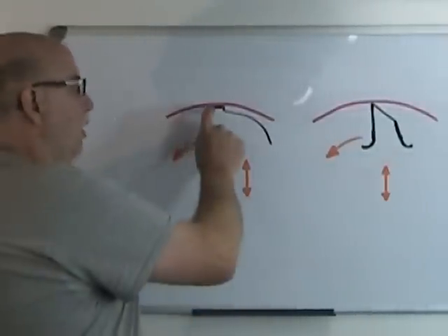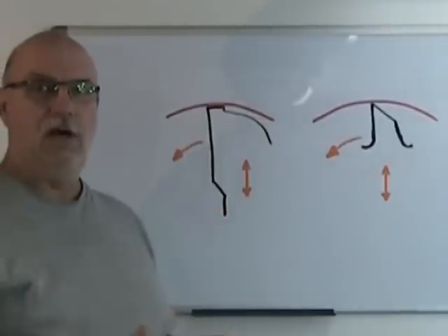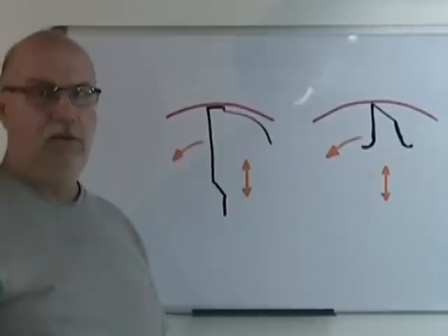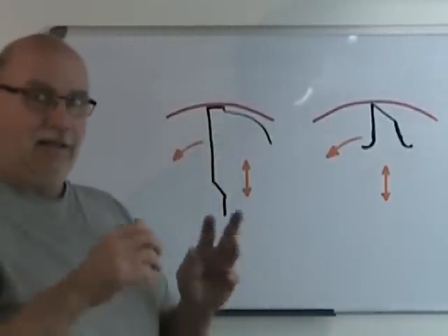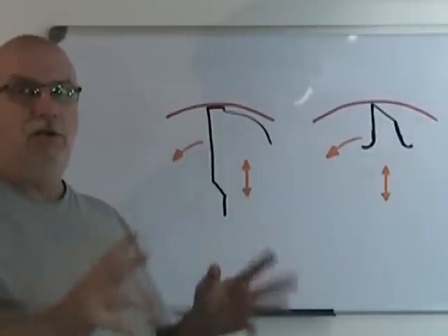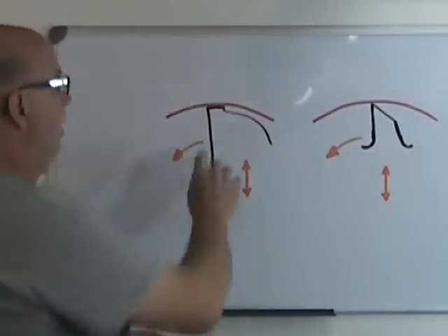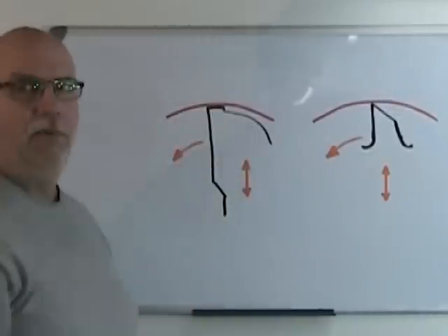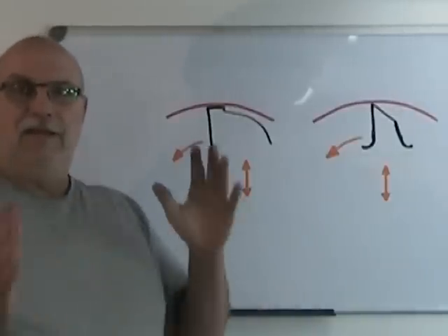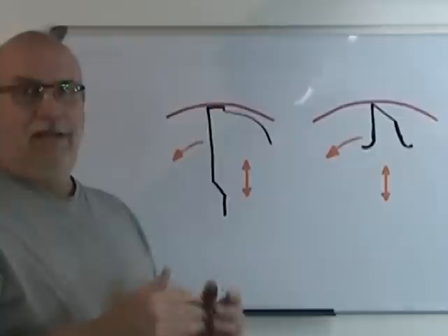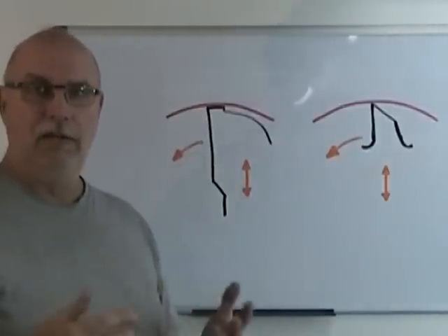Now, if these were cutting edges, the minute that the chisel edge would stop tracking the drill in the hole, they would start cutting and grabbing, and that little chatter that we get would become a huge chatter problem, and it would be enlarging the hole. Whereas rounded out margins that don't cut, well, they tend to keep the drill in the hole, and even if it rubs on the side, it won't enlarge the hole any more than that.